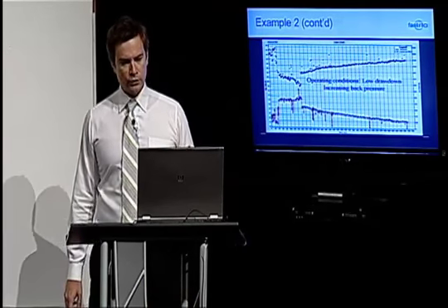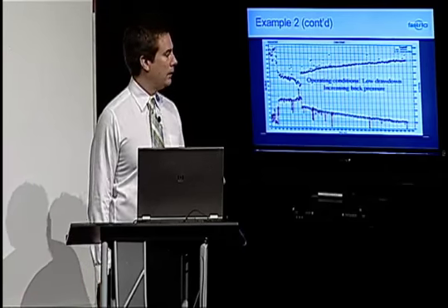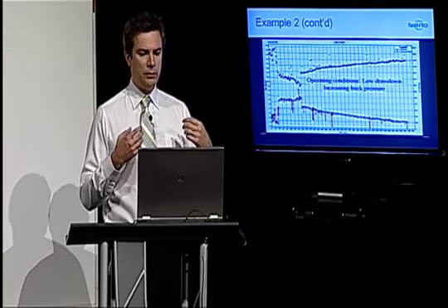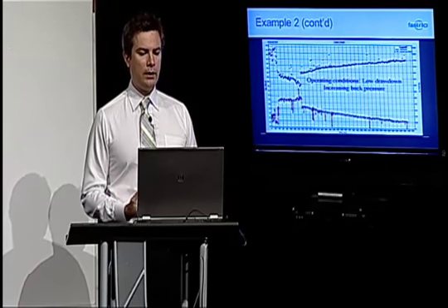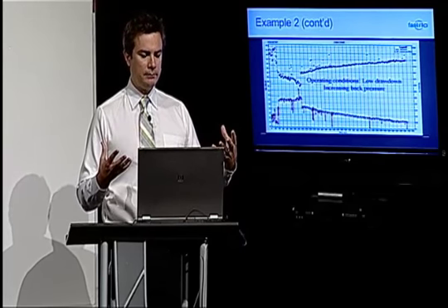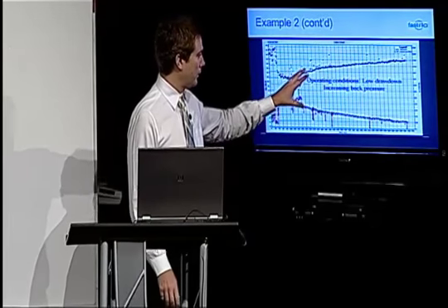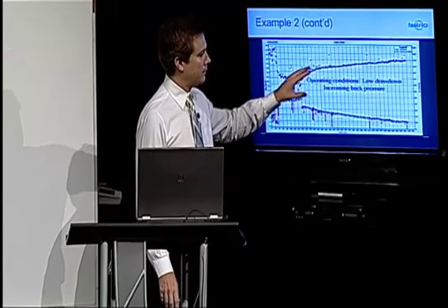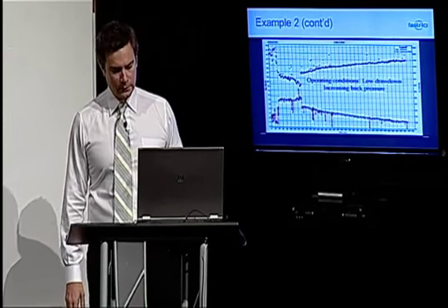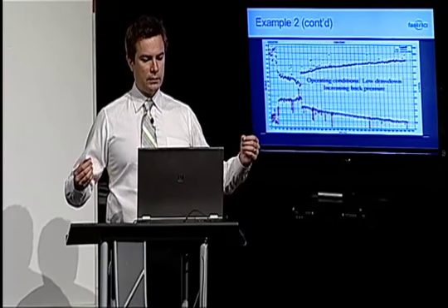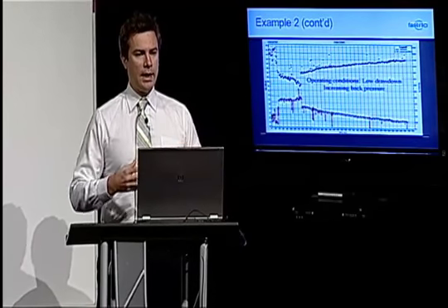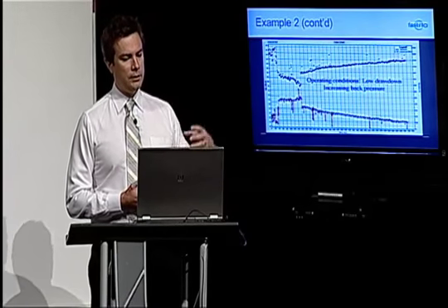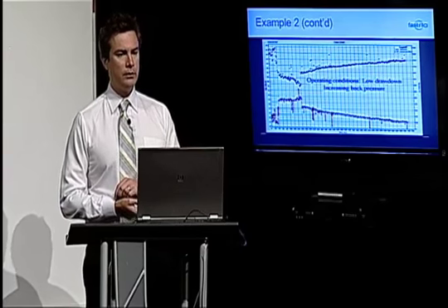And what's actually happening in this example is this well was drilled into an area where there was a gathering. Well, this well was drilled earlier, and the gathering system that was accommodating this well's production was inundated with additional gas from new wells that were drilled into reservoirs with higher reservoir pressure.